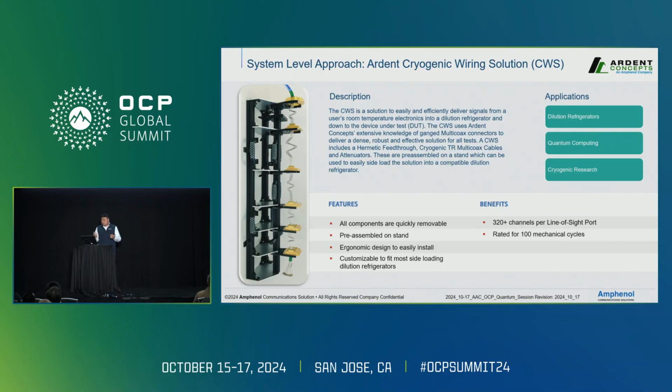In this example, the compressive solution starts at a hermetic feedthrough and includes the wirings and microwave components connecting at each stage of a dilution refrigerator. To ensure the best user experience in this critical and complex system, a wiring solution like this will be custom designed to be mechanically installed in one piece within the specific fridge that the quantum computer deploys. While the individual components remain modular and easily accessible for service, they're pre-installed on a custom-designed mounting fixture and rigs, fully validated electrically and hermetically tested prior to shipping. This approach minimizes any risk associated with shipping, handling, and the user's first install.